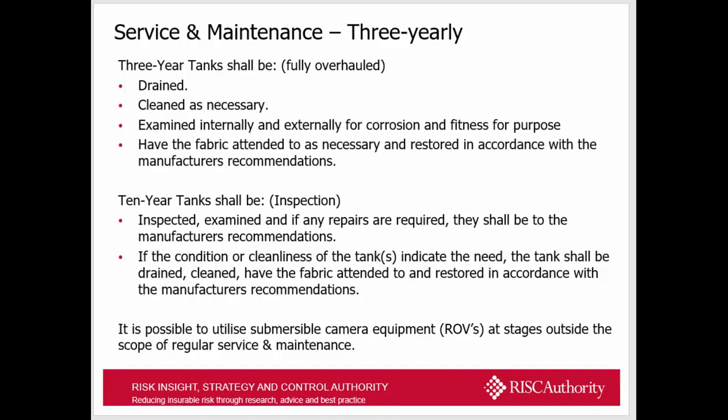And if you have a 10-year maintenance-free tank, you shall inspect it on a 3 yearly basis, again in accordance with the manufacturer's recommendation. However, if the condition or cleanliness of the tank indicates that there is a need, the tank should be drained, cleaned and have the fabric attended to in accordance with the manufacturer's recommendations. However, in TB 203, it is possible to use submersible cameras, ROVs, outside the scope of regular service and maintenance, to inspect a 10-year tank.